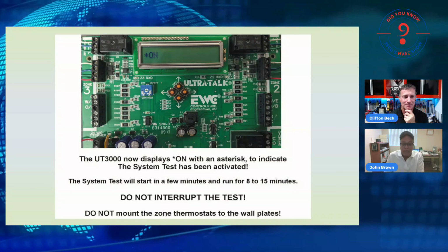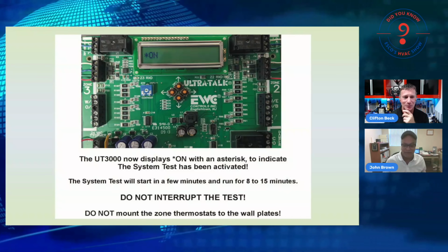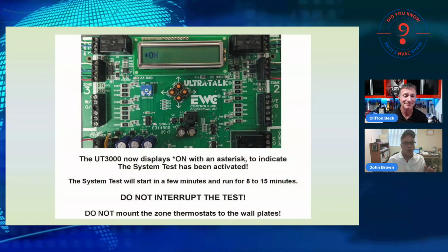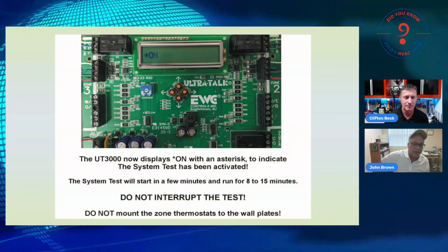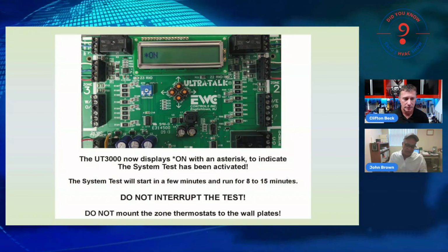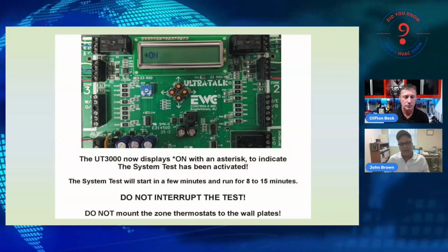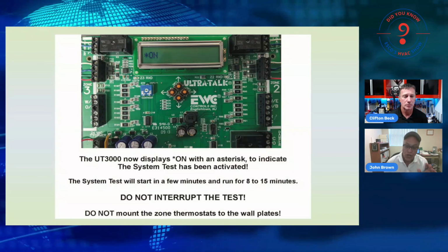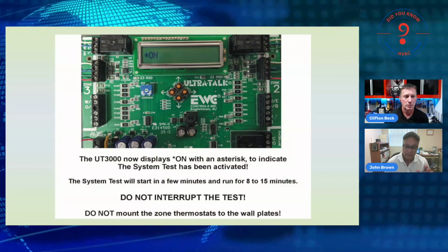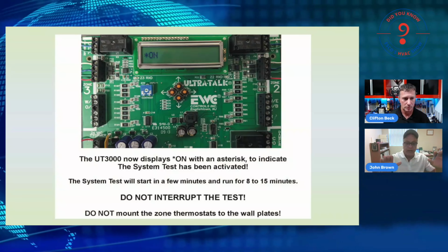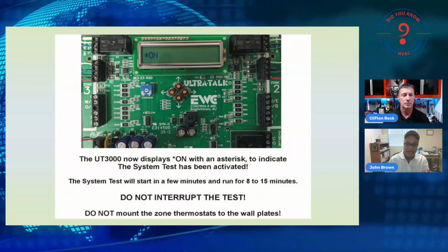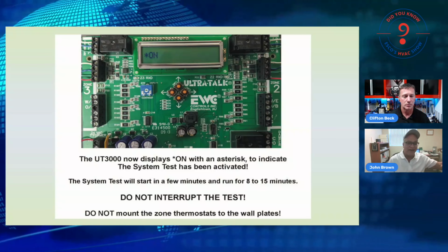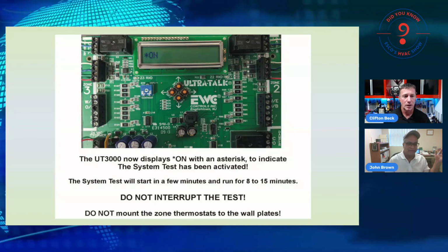Exactly. Her damper will remain open, but other zones are going to close off. You don't want to affect the outcome of the system test. So 8 minutes, 15 minutes, clean up the area a little bit, and then come back. Now, you'll know this test is done because the equipment will simply go idle. Right. And the E11 display outside is gone.